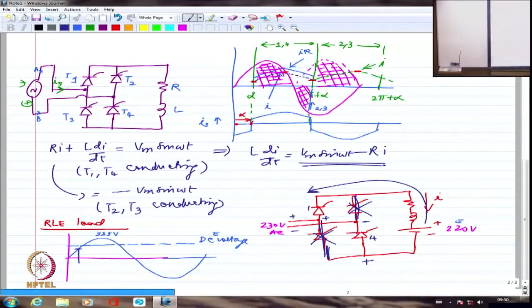So if that voltage appears here, I have to have a tug of war between these two, whether this is dominating or that is dominating. If the voltage here is dominating over this positive, then it is reverse biased. On the other hand, if this is going to be smaller, I will have this forward biased.